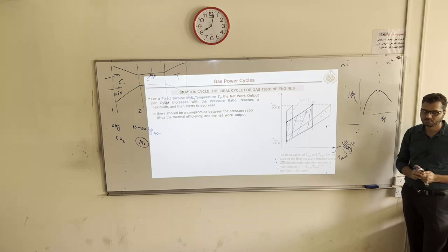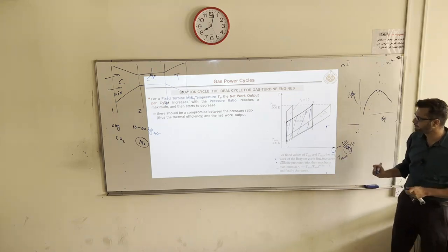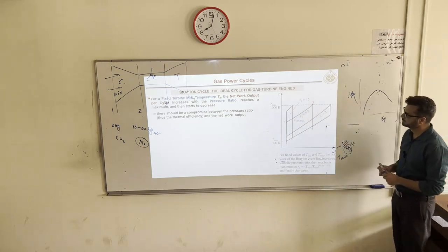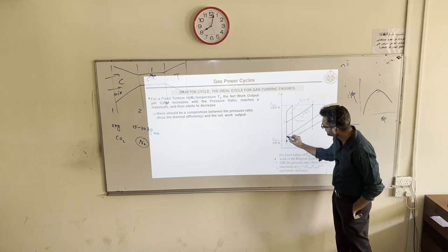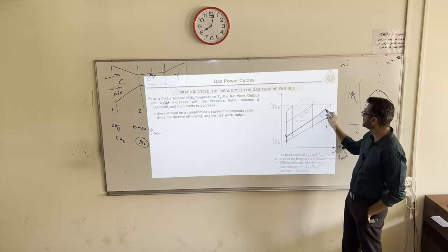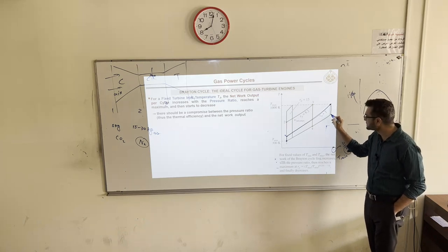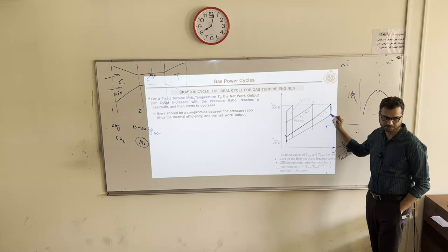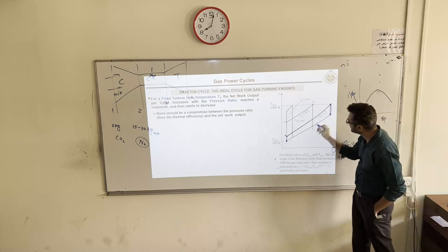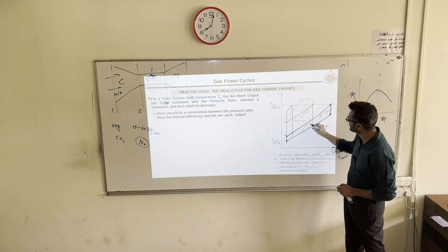Can you repeat the relationship between T maximum and the previous graph, how it affects the efficiency? Okay. How it restricts it? Okay. So for example, if your pressure ratio in the compressor is this one, very small pressure ratio, then this whole heat you supply in the combustion chamber to reach the maximum temperature which we want, and then there is expansion in the turbine. Okay, and then it is exhausted, and this exhaust we have replaced with heat rejection process. Okay, so this is the net work done I can get.